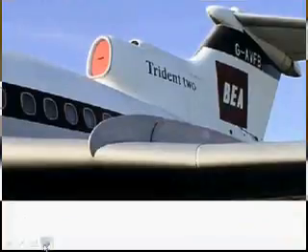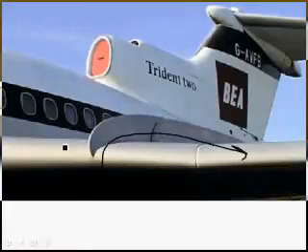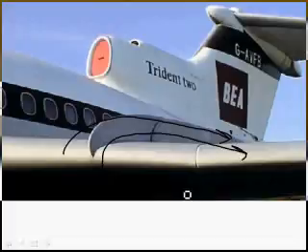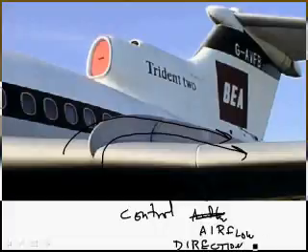Wing fences. There are not a lot of airplanes with wing fences. Here's one, I can't remember the name of the aircraft, just made in Great Britain, but it looks like a 727. It's called the Trident. It's got a big giant wing fence. Obviously, the airflow going across the wing is going to go exactly where they want it. So it's going to control airflow direction on the wing.